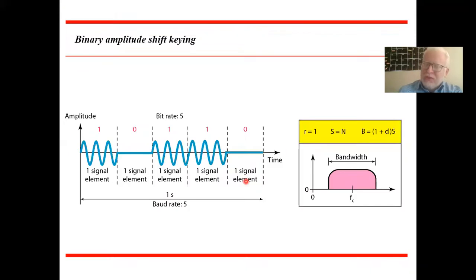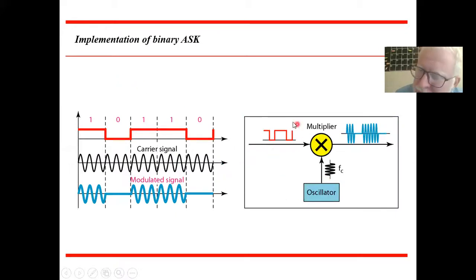So let's start together. First, let's start with the first and easiest way to modulate a digital signal, which is called amplitude shift keying. Here we call it binary amplitude shift keying because basically our digital signal is in the form of binary bits, ones and zeros. That's why we use the word binary. So if you remember from the basic understanding of AM modulation from the analog perspective, the modulation process is simply a multiplication between the message and the carrier.